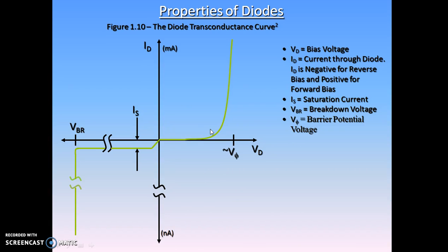Okay. Now when the forward voltage exceeds the diode's PN junction internal barrier voltage, that is 0.7 for silicon, avalanche occurs and the forward current increases rapidly as shown here. So for a small increase in voltage, there is a very high current. Likewise, when the diode is reverse biased, that is cathode positive with respect to the anode,